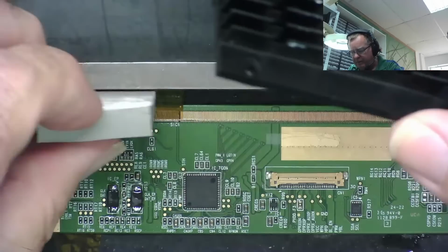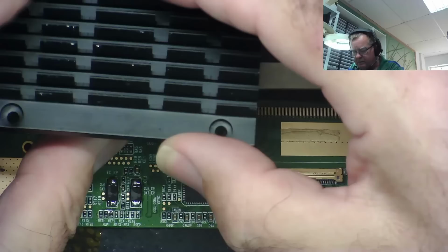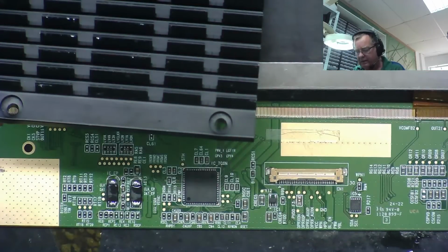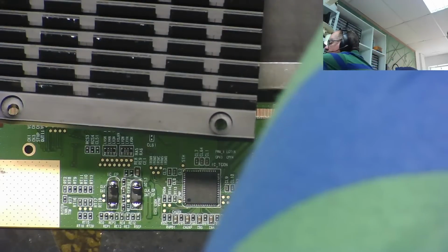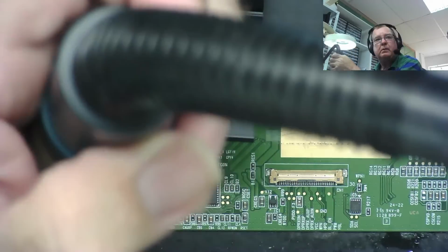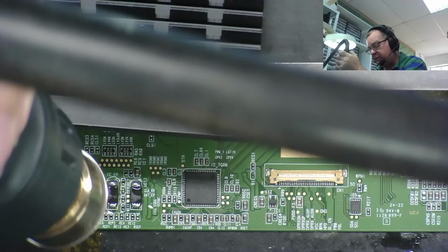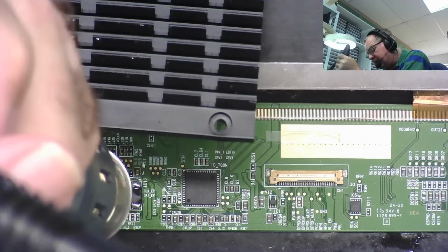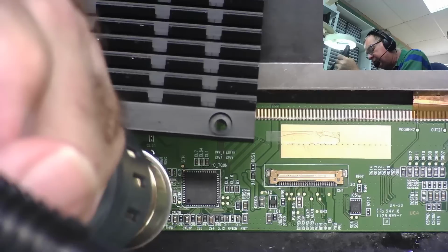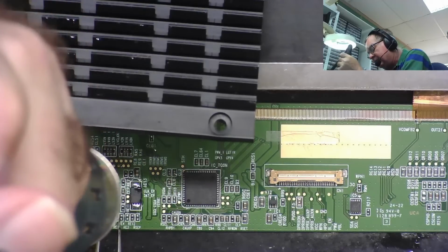Straight away, the little rubber things fell off. Try again. Okay, let's see if this will work or not. I may be better coming in left-handed with the heat on this one and right-handed with the tweezers. So let's get some heat into this area of the board. We should see the leaded solder melt, and when that happens, we can remove the chip.